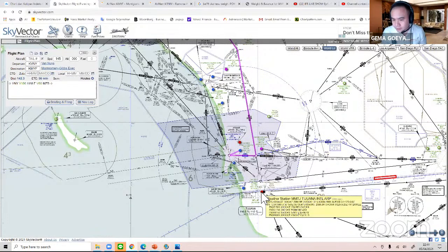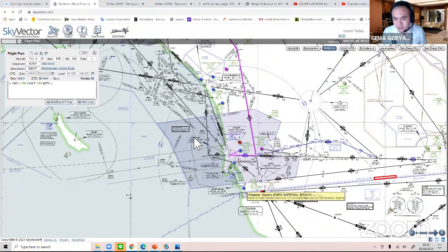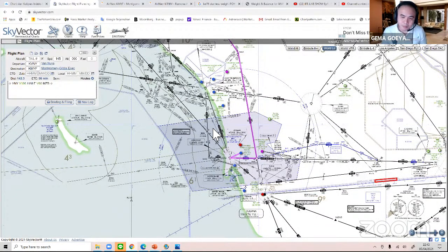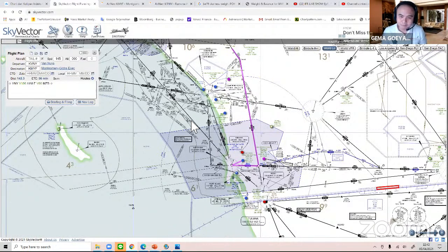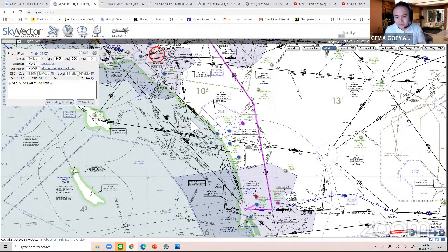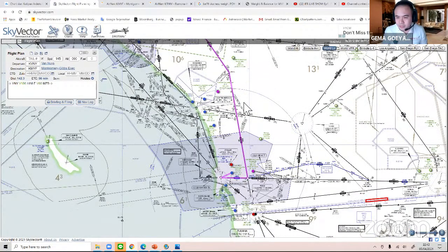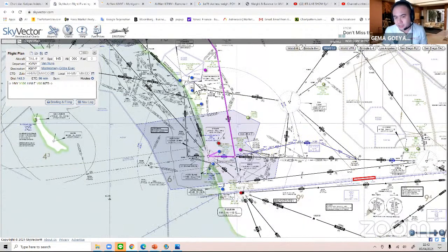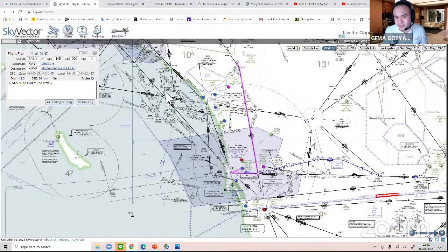Tijuana International Airport is IFR. Imperial Beach is marginal. So based on this data, you can most likely predict where the clouds will be, where the ceiling will be. It's likely getting clear, but it's moving to the southeast, right? The weather system has moved to the southeast.